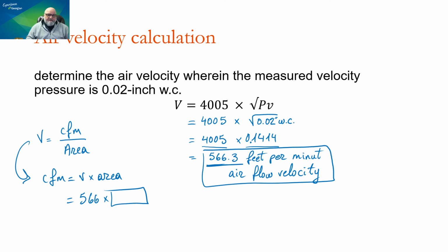In the residential, it's easy to target airflow. You look at the filter, you look at the blower, you look at the A coil. You can put things together quickly in terms of troubleshooting. But in commercial, you're going to find that airflow is absolutely critical.